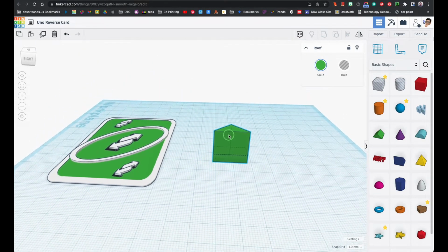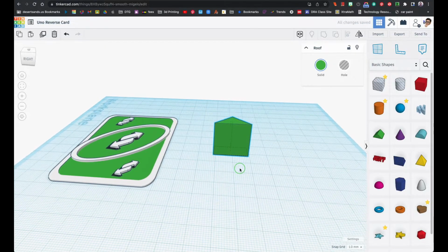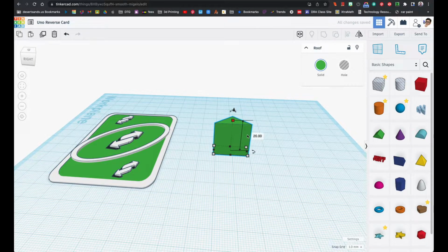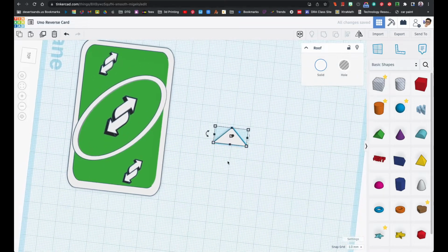Now, if you notice, when I rotated this, half of this went under the printing area. I'm going to click the letter D to move it directly on top of this area. So letter D, and there it is. I don't have to worry about that anymore. And one last change I'm going to make is make that 1. I clicked on the center 1 and then the number. Click the number 1 and hit enter. The next thing I'm going to do is I'm going to change the color to white, because I already want it to look like that, and I'm a little impatient.